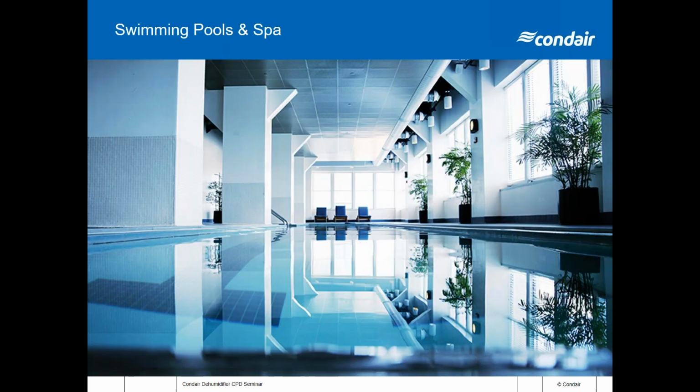Swimming pool dehumidification, again, is another important application where we want to avoid condensation, because that's going to lead to rusting and damage to building materials. So dehumidifiers are usually employed in private residential or hotel swimming pools. Larger swimming pools are typically controlled through air handling units. However, all do need a certain amount of air circulation, so typically between 3 and 7 air circulations per hour.